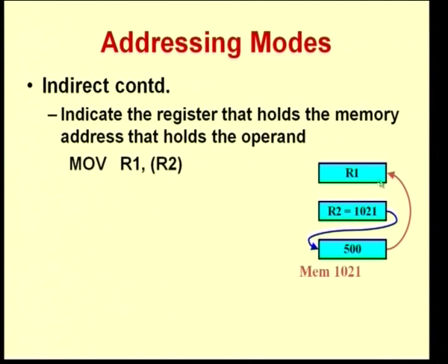Similarly, we have an auto decrement addressing mode. So, you say minus again in brackets R2. Again remember that I have put a plus on the right here and a minus on the left over here. The reason is that here what we normally do is you first decrement the register R2 and then you access the contents of that register. So, we call this a post increment, and this is normally referred to as a pre decrement. These are two variations that we have of the auto increment and auto decrement mode. Sometimes of course, you could also have the other way around, but this is the normal convention.